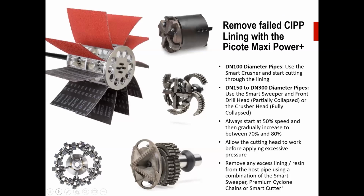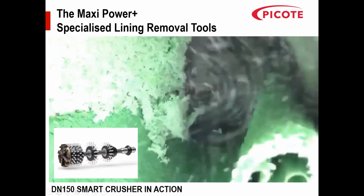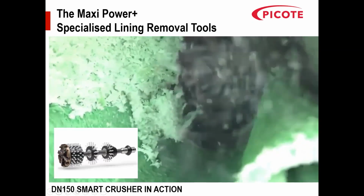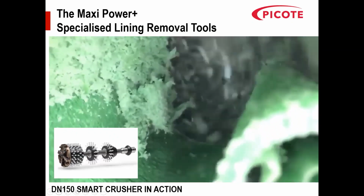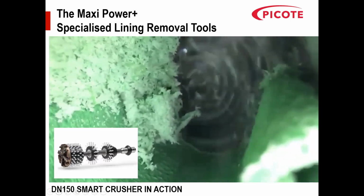So if you're unfortunate enough to have what we call a failed liner, then we've got tools that are used for that. Generally, we use a combination of drill heads and the Power Plus. Here's a good example of the machine being used to cut out a failed liner. You can see how it's chipping away at the liner, cutting it into little bits. Depending on the type of liner, we can remove between 3 to 5 meters in a session, an hour.